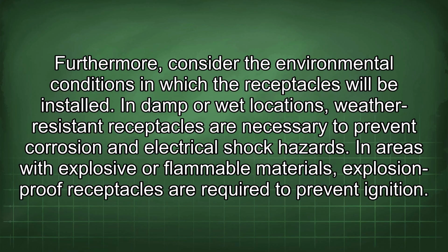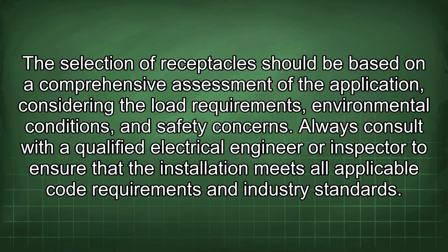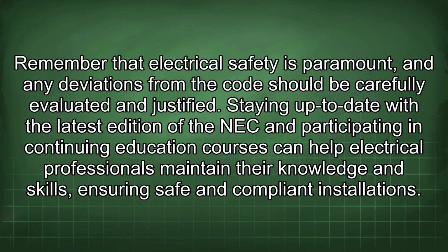In areas with explosive or flammable materials, explosion-proof receptacles are required to prevent ignition. The selection of receptacles should be based on a comprehensive assessment of the application, considering the load requirements, environmental conditions, and safety concerns. Always consult with a qualified electrical engineer or inspector to ensure that the installation meets all applicable code requirements and industry standards. Remember that electrical safety is paramount, and any deviations from the code should be carefully evaluated and justified.